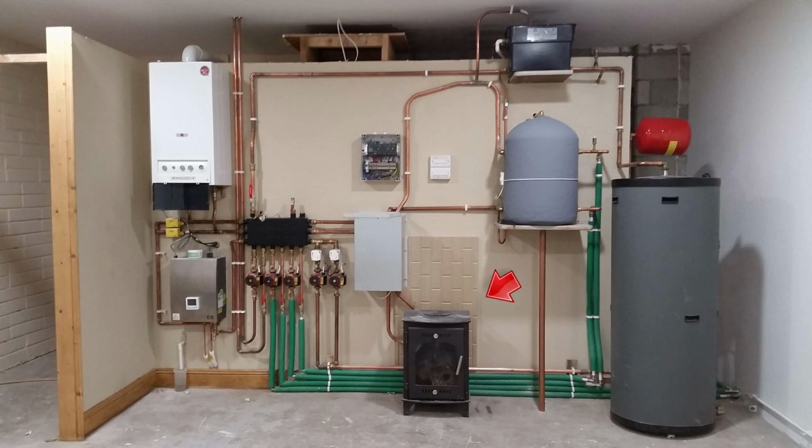There's the solid fuel fitting in on one side, and that's a sealed system, open system on this side. A gas boiler working at, it was delivering, if I'm not mistaken, 70 degrees, was it, Rich? Yeah, 65 to 70. The heat pump was putting in at 45. The gas boiler was putting it up to about 60. And then the solid fuel was taking it and putting it up to 70. So we were actually delivering 70 and taking back about 35, and everything was working hand in hand.